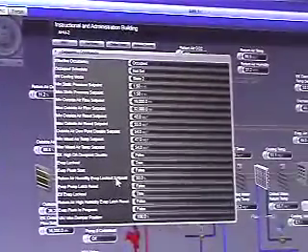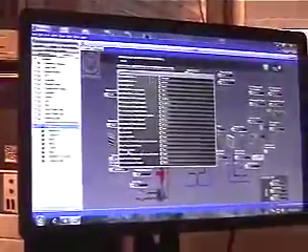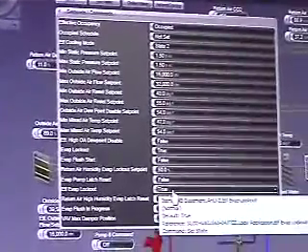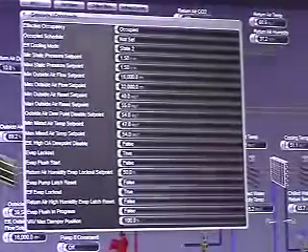You also have the ability, so return humidity lockout set point is 50%. So we're running, all of a sudden it got about 50%, our humidity got too high in the return. We then, I'm done, skip the state, go to state 4. On its way back, it's just going to skip over that state as well. Your effective evap lockout is really, that's not the command point, that's just your effective state. That's letting you know really what it's doing.